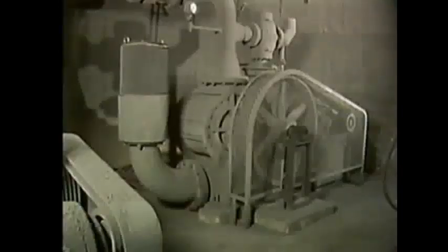Compressors often have devices or systems that remove foreign material from gases, remove excess heat, and provide lubrication. For example, filters are often used to remove foreign material from a gas before the gas is compressed. If small particles of dust or other foreign material are allowed to enter a compressor, they can cause the compressor to wear excessively and eventually fail.